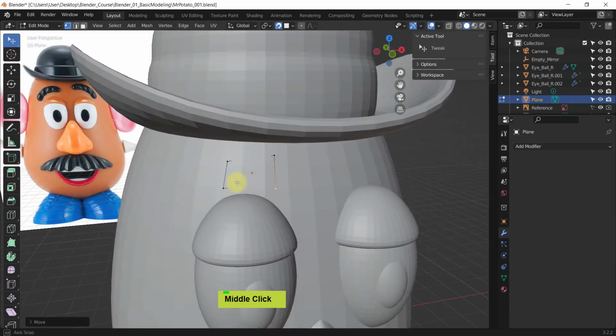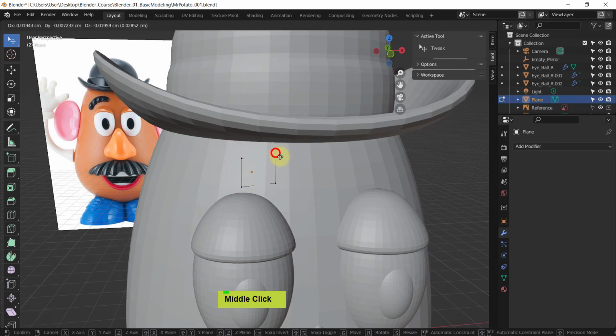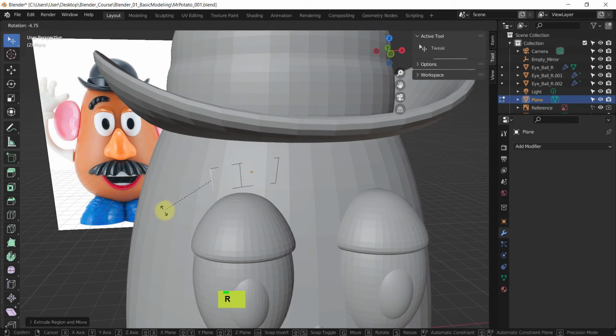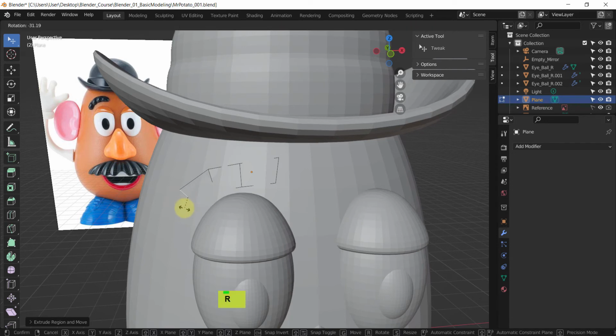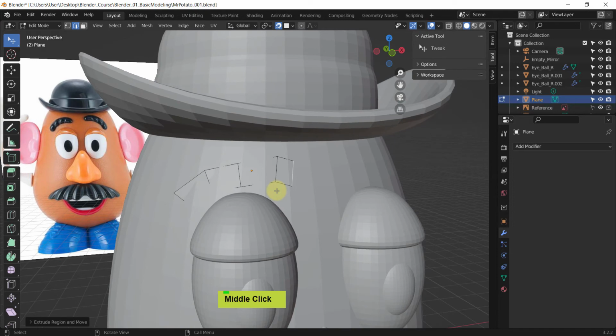And here we have another one. This one is already sinking kind of into the surface. This is the elemental polygon, so it's not enough. We definitely have to extend this. So go to edge mode, select the edge, press E to extrude, and right away, if I wish, I can press R to rotate it slightly, then E and drag it, and E, R for rotating it slightly. I will create another one maybe here, so E and drag this out. Okay, so this is where we are.